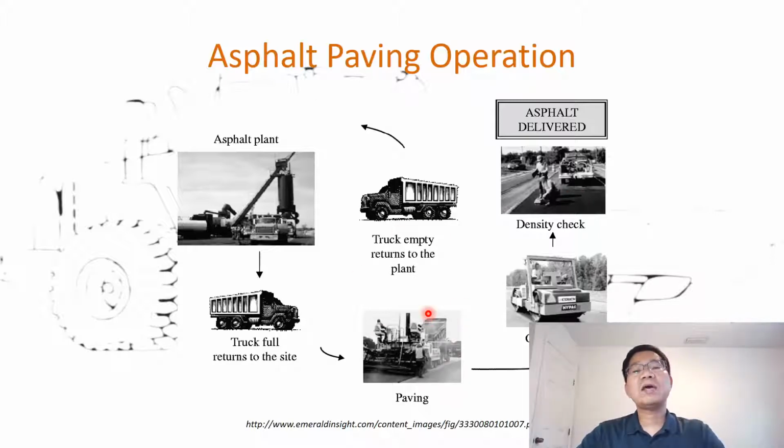In this case, there are two critical choke points that normally need to be considered, because to improve the efficiency, we want to have continuous operations. So what does that mean? Continuous means the balance between the production of the asphalt and the production of the pavement on site. So with that, we need to consider two choke points or bottlenecks. The first is the link between the plant and the truck, so that it loads with no waiting time in there.